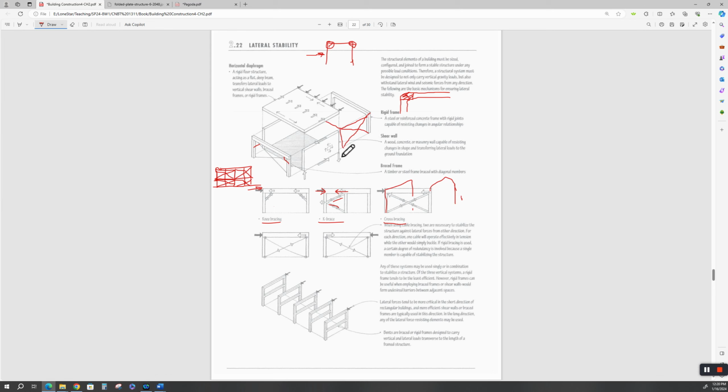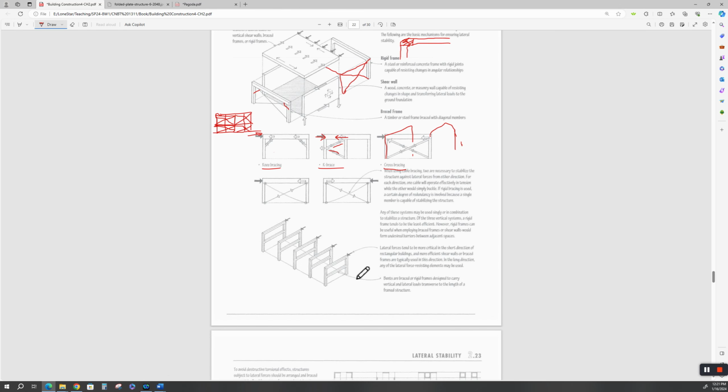And you'll see a lot of this K-bracing like that will be cables, heavy rods with turnbuckles once they get the framing up. And then you let your roof system take care of the shear. And then perhaps if it's super long, depending on your wind loading, you may need a concrete wall, solid shear wall like that periodically through the span. Your imagination and creativity is endless with this stuff.